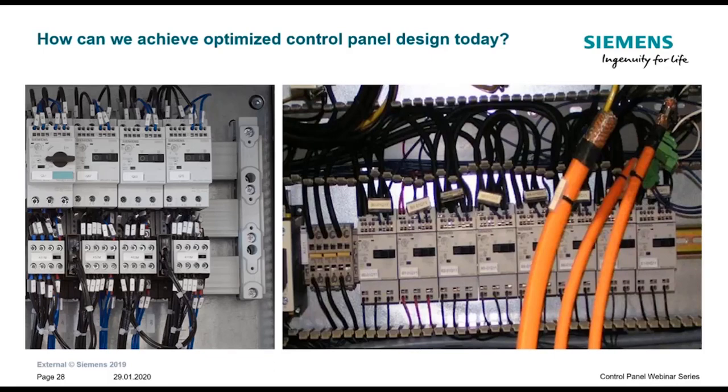Well, solutions like the ones in these two images were found in control panels until recently. Actually, you can still find them like this in the industry today. It takes a lot of time to wire the components in these cases, but this is not the only factor. The time you need for such configurations starts a lot earlier when you're actually measuring spacing, cutting cables to the right length, marking, and a lot of other things that you do before actually cabling.